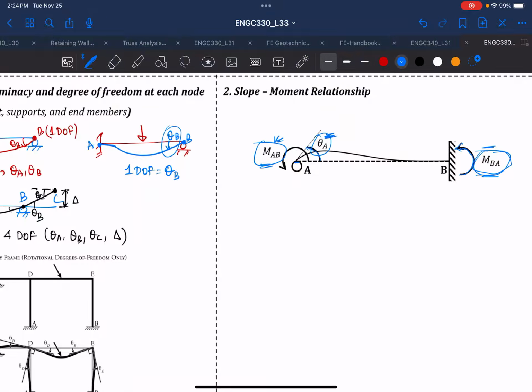So in this case, the concept behind deriving this equation is we use the concept of splitting the member into a determinate structure and then use conjugate beam theory. So how do we split into a determinate structure is by converting this into a determinate structure, which is your simply supported beam, and then we apply a moment MAB, and this will be your reaction.